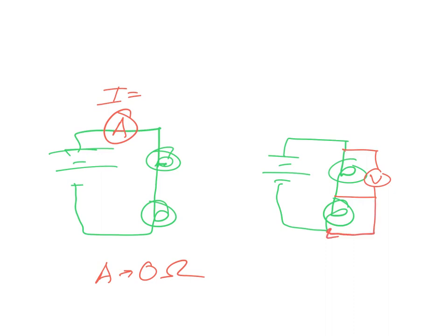It tells me my potential before and my potential after, so it'll give me the voltage drop across that component. And for a voltmeter, we assume that it's essentially infinite resistance. That way it's not drawing any of the current to leave the circuit and go through the voltmeter instead of continuing to go straight across the light bulb.